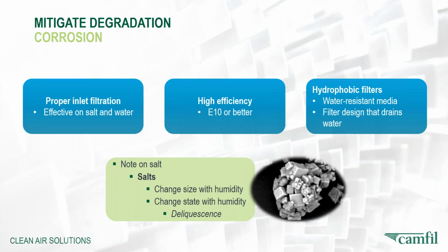A quick note on salt is that salt's kind of an interesting contaminant or particulate, at least for the filter engineer. It's not stable. It will change its size with respect to humidity. If we have a submicron salt particle and humidity increases, the size of that salt particle will increase. Salt is hygroscopic. It has an affinity to water vapor, and it will grow in size.